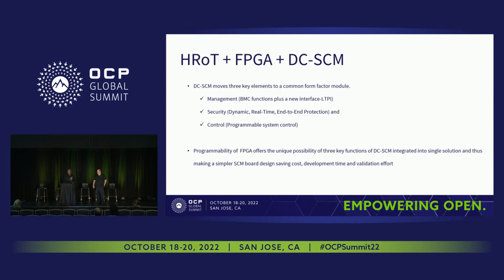So that's the whole idea here, is that the FPGA already serves power sequencing, and that's a big one, right? That means I'm holding the sub-platform on, and I'm the only one who's allowing the platform to boot up. So why don't you also make it the security root of trust? You need the security root of trust to be at the very beginning. You cannot put a security root of trust like a TPM after the boot event. Well, it can have some functionality, but you are out of luck if something is bad. You have to have manual intervention on the servers to go there, right? So you want something in the beginning to boot up from, that you know is trusted. That's the distinction between a TPM and the hardware root of trust that we're proposing.